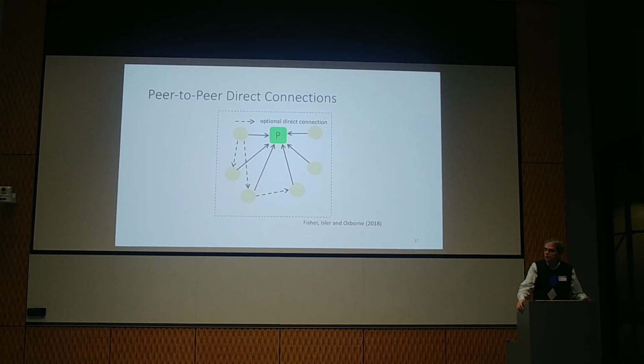Now, for performance reasons and for reliability reasons, we wanted to also enable peer-to-peer communication between devices. Now, this is not a requirement for every device. If you have a BACnet SC light fixture, you might not bother to implement peer-to-peer capability in it. But for more sophisticated devices, you probably would.